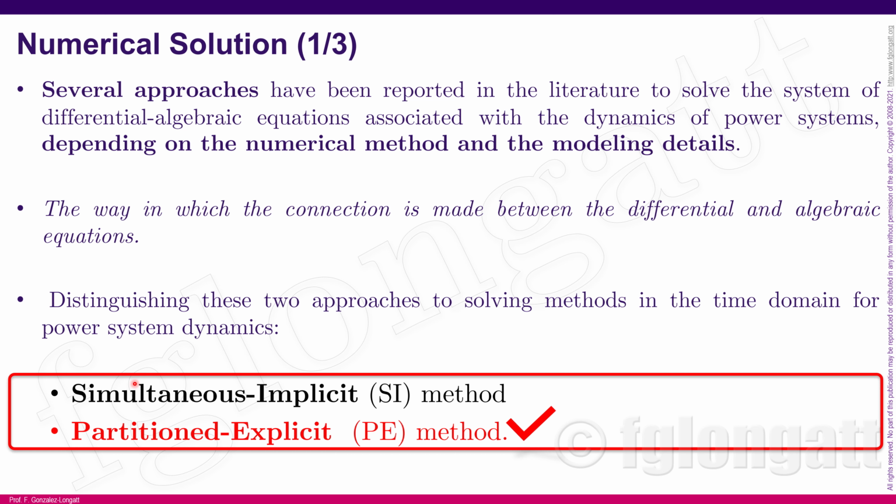The most used method is the partitioning explicit method. We talked about this method many times in classes. It is extremely simple. We already have very good algorithms to solve the network equations, for instance the load flow, and very good numerical techniques to solve differential equations, for instance Runge-Kutta and predictor-corrector. What partitioned explicit does is solve the differential equations, then solve the network equation, and again and again.